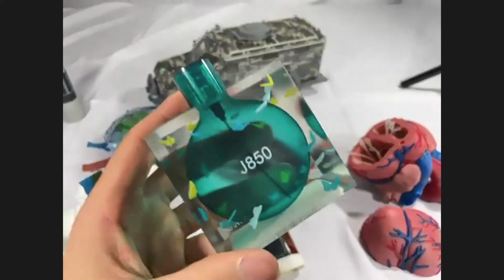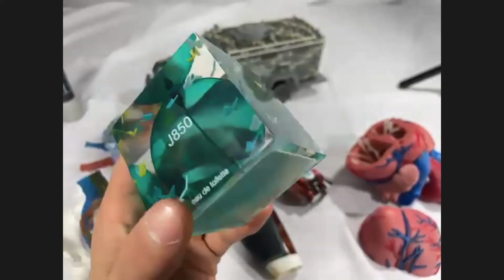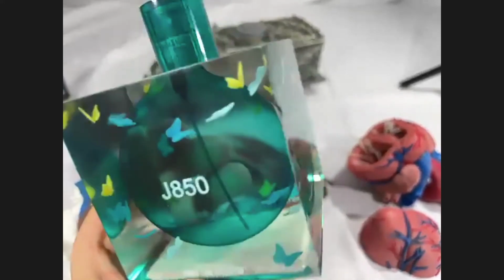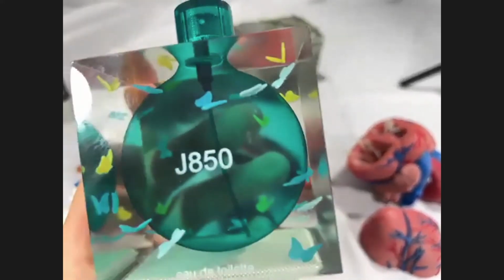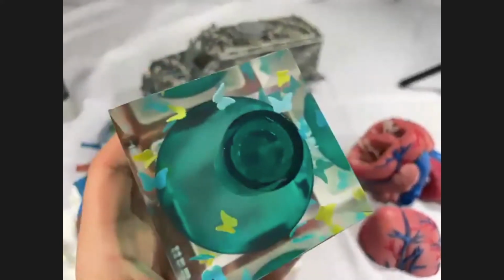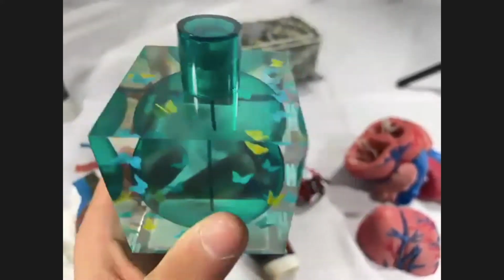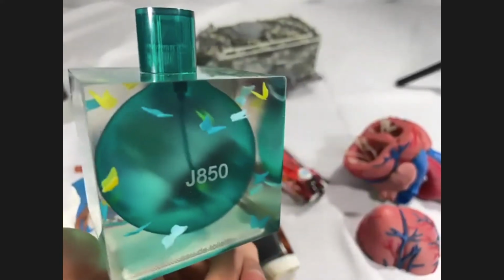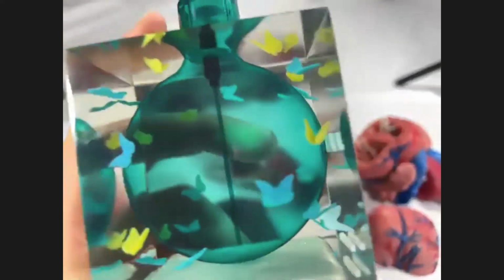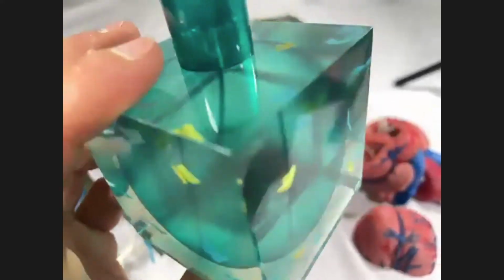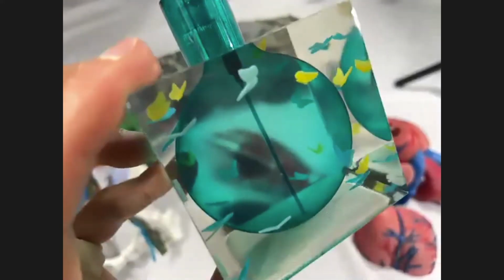That's one where we're using the ultra clear feature of the J850 with some post-processing. Post-processing is basically sanding with some fine grit sandpaper, and then you can do some processing directly out of our back room. We can handle all that for you. You don't need to get your printed parts and then go seek a secondary post-processor. We have those capabilities and can quote those jobs for you directly. So as far as the 850 capabilities of ultra clear, this is a great example of that.